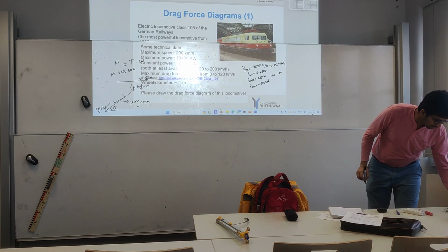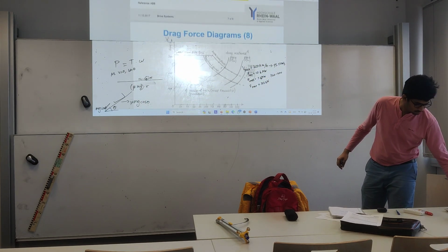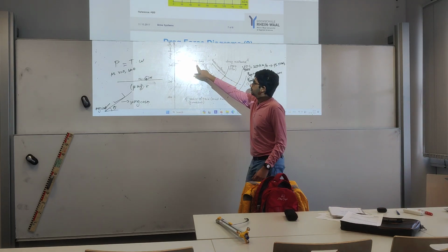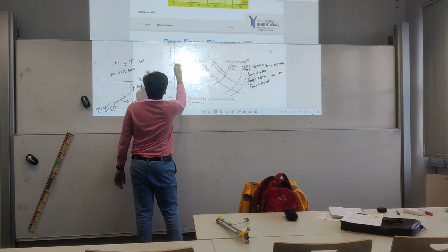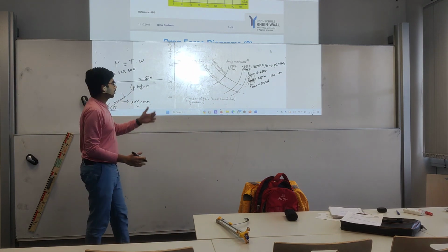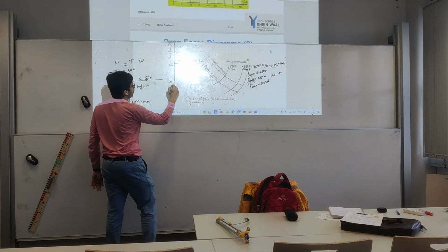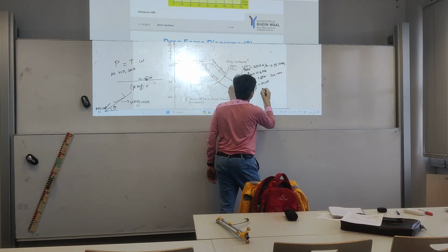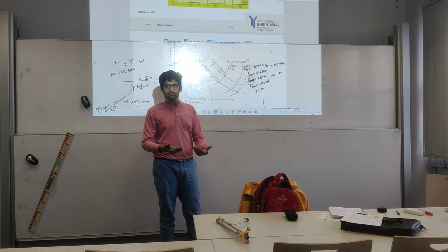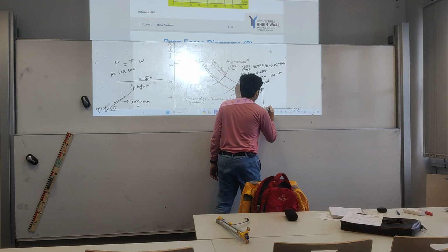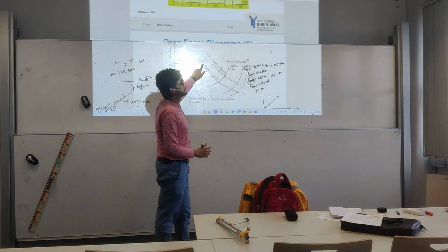So in this diagram we have three constraints. The first constraint, like I mentioned before, was from the friction, and the next constraint happens because you are keeping the same torque because the force is same. What is torque? It is force times radius. So that force is coming from this point. So F r is the torque. If I look at the power graph, power versus velocity, initially it's making zero power because it's not moving, but it's making some torque. Gradually it increases. At some point it reaches the maximum power that it's able to deliver.